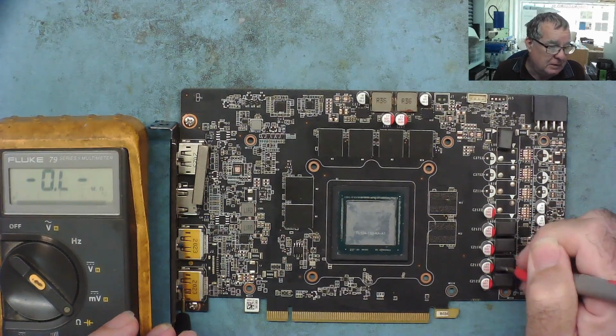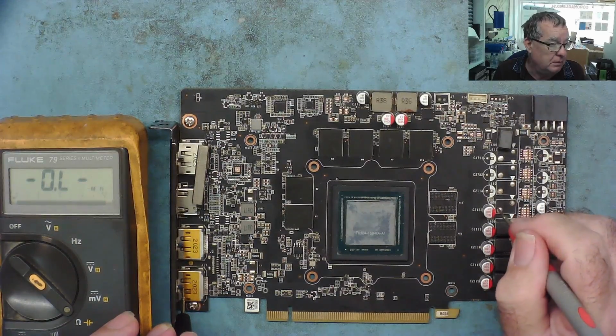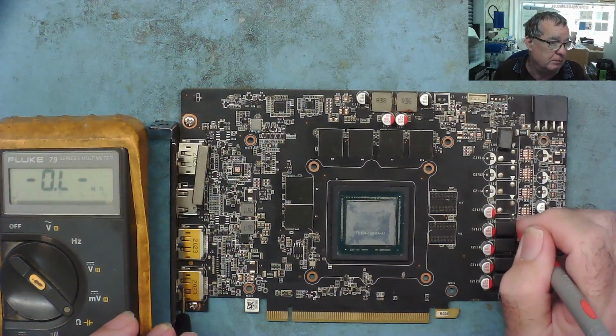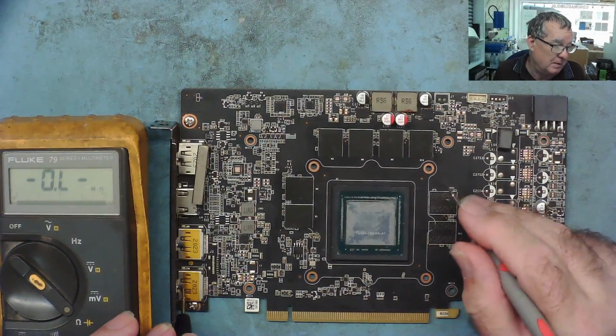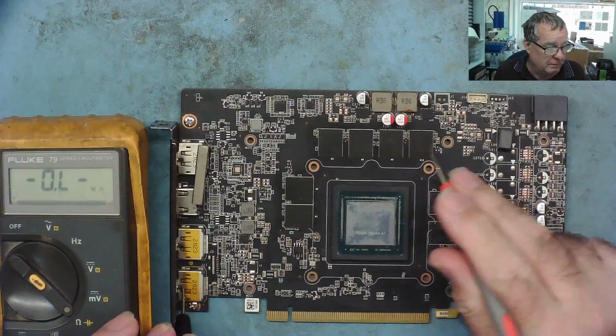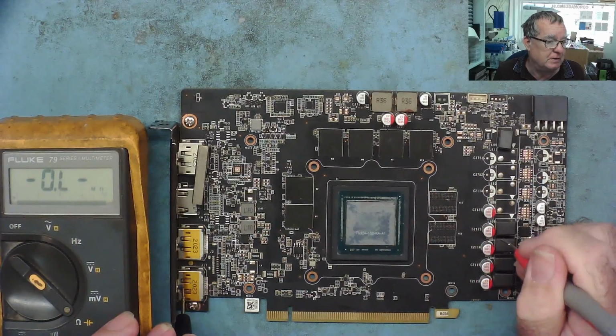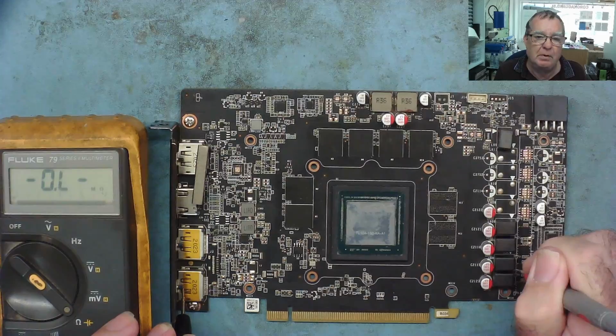This board in fact only has four phases down here, but it's common to have graphics cards and motherboards with 8 phases, 10, 12, 16 phases maybe on some very high powered ones. And when you get to these sort of boards with many phases, it is important that you can determine which high side MOSFET is the faulty one.